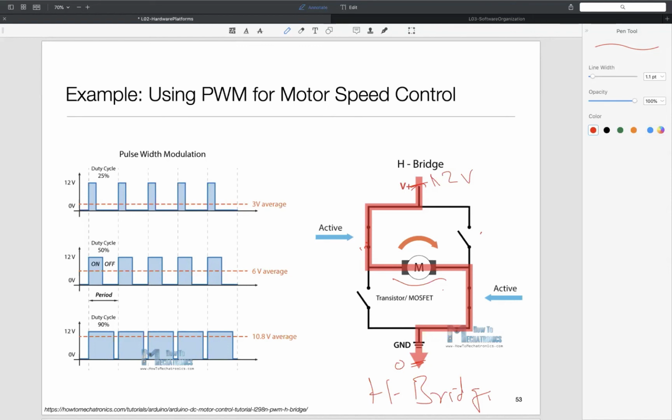So this kind of H-bridge structure, where you're using some switches and usually some transistors, does the trick very nicely. You can do speed control, position control, intensity control very nicely. What's the gotcha? To convey an analog value, I need a significant amount of time. In the previous example, I used 1 millisecond, which means I am wasting a lot of clock cycles.